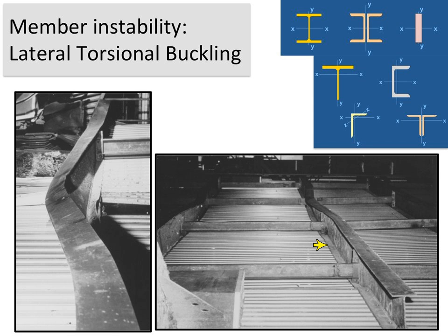Unfortunately, at some point or another, things went wrong, and the system was run incorrectly. At that point, instead of there being an upward pressure, there was a downward pressure. And when this downward pressure occurred, just the opposite happened. Now the bottom flange was in tension and the top flange was in compression.